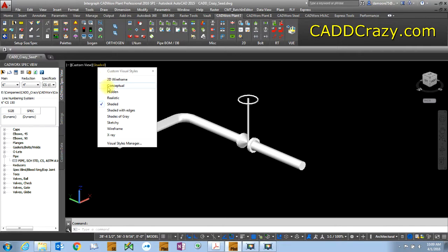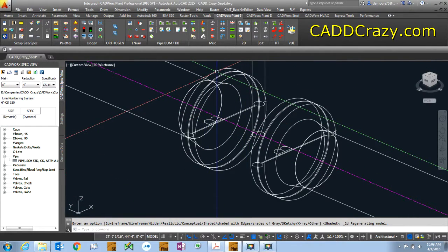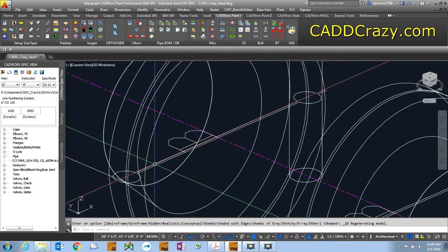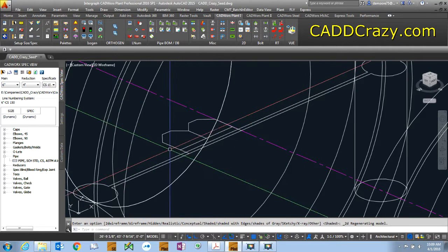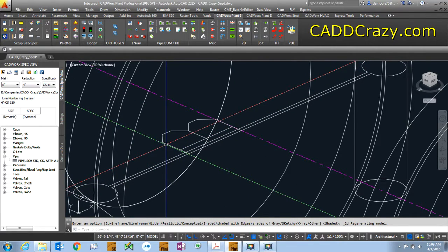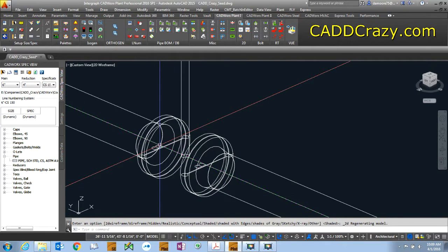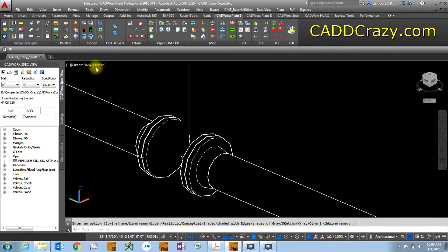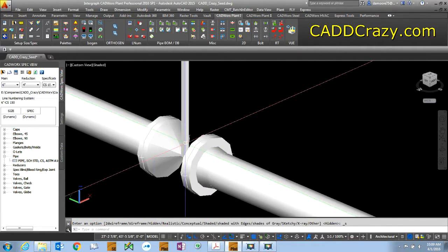Well, what it does is it gives you your flange and your valve, but it represents the gaskets as this little squiggly line right here, and this B as far as the bolt. Imagine that. So again, functionality wise, it works fine. You drop it out on ISO, it's going to come out with the right bolt lengths and bolt count, right gaskets. But when you're doing a model review with a client, it's not that great. I mean, it just shows you where everything is.